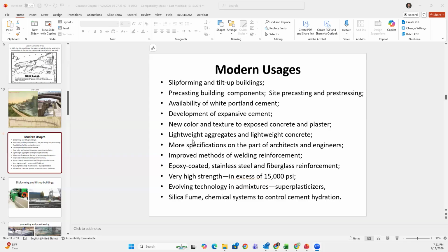So concrete has at least two pluses versus wood. Stronger than wood, more fire rating than wood. So small buildings, you build with wood. But when you have to deal with a large building, where the fire rating is important, you lean towards concrete.